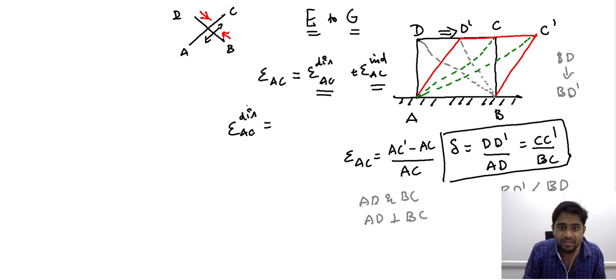In this case, we are considering the tensile load, and we have only imposed the shear load here. This shear load is what translates to the tensile load along AC. So let me repeat, we are imposing only the shear load, and this shear load is what translates to tensile load along AC. Therefore, we can write the direct response of AC as the ratio of the stress and the corresponding modulus.